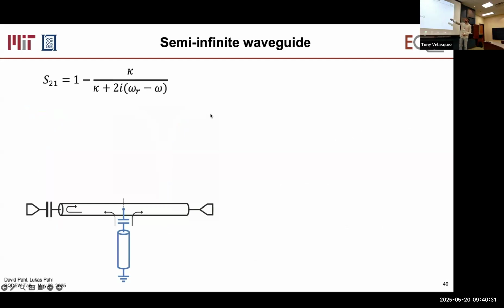So this formula here is only accurate if your resonator is coupled to a perfectly matched feed line. So something like I showed on the previous slide. If there are no impedance mismatches on this line, then our Lorentzian will always look perfectly symmetric. Now, if there are impedance mismatches on here, that'll introduce asymmetry into your Lorentzian. It'll look weird. I'll show some plots. And we can extend our model by a parameter phi, which introduces this asymmetry, a phase roll.